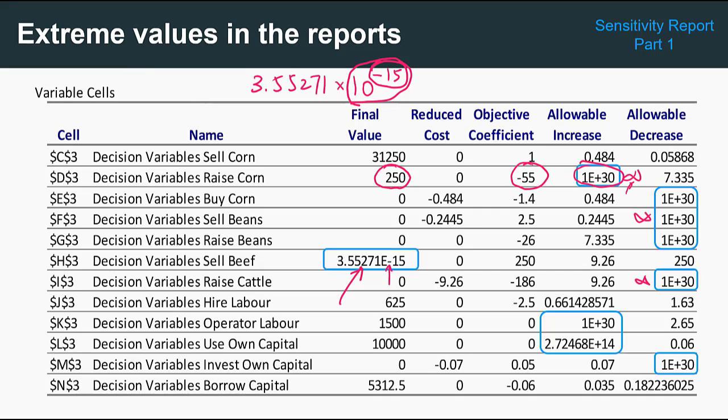That's why if you multiply this number by 0, it's 0. Even if the solution is reporting this value, you should interpret it as a value of 0. You may say, oh, those are zeros, but this one is not. That's not correct. It's just Excel's way of saying 0. So this value is really 0.